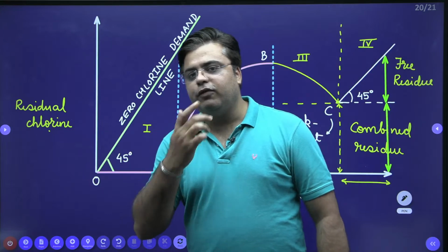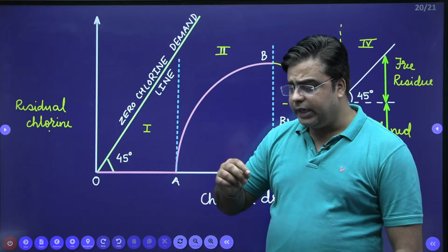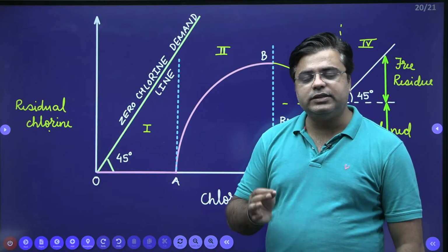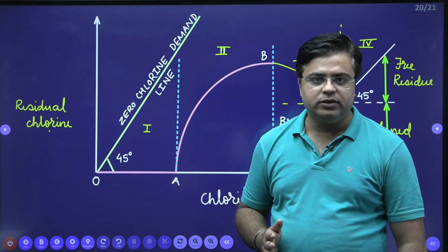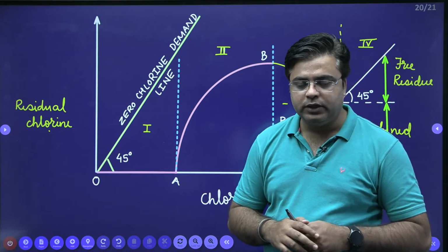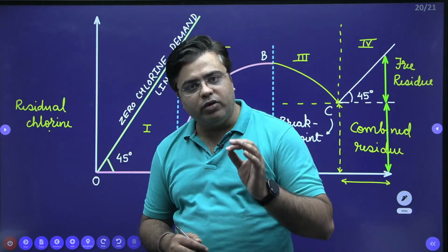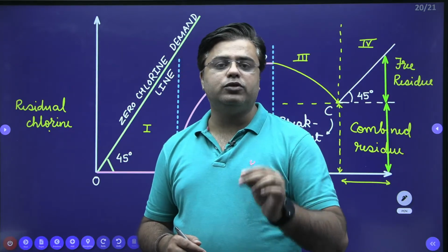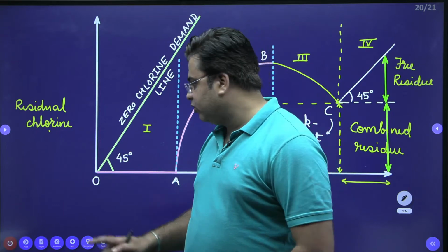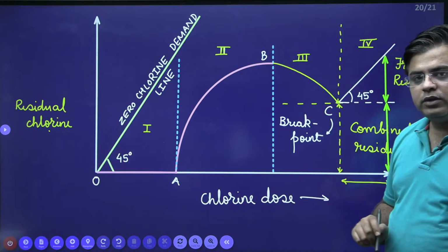Now, one of the favorite questions asked in the examination is in which section disinfection is taking place. So you have to be very, very careful in answering this. The moment you have added chlorine, the free forms of chlorine will carry out the disinfection from this point till this point.